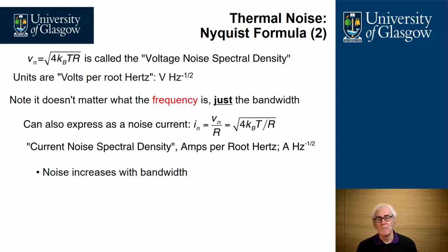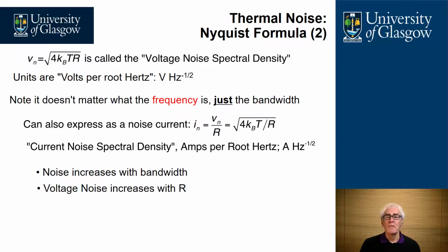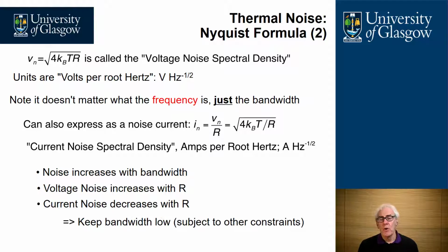Voltage noise always increases with bandwidth, resistance and temperature, whereas current noise always decreases with resistance. So in any given design, you should try and keep the bandwidth as low as possible, as long as it can deal with the application, because that will reduce the noise level from your circuit.